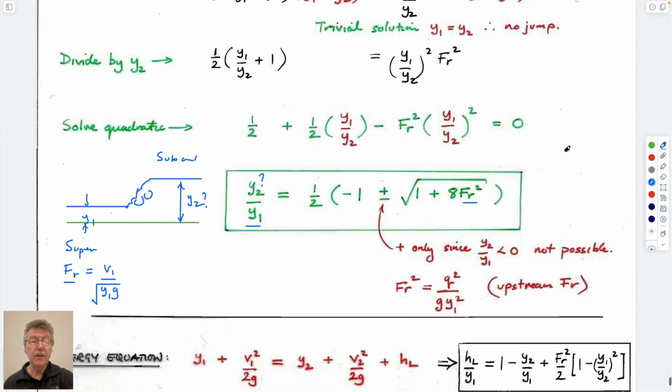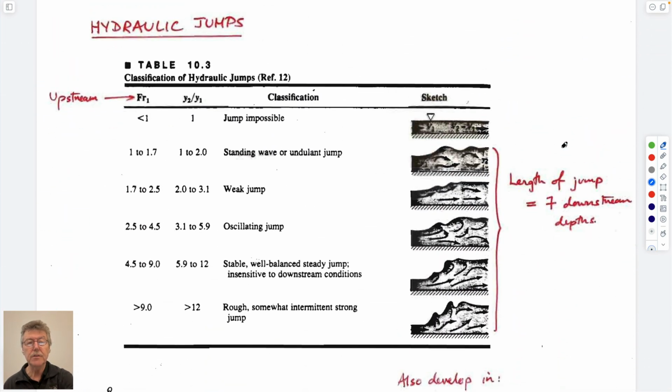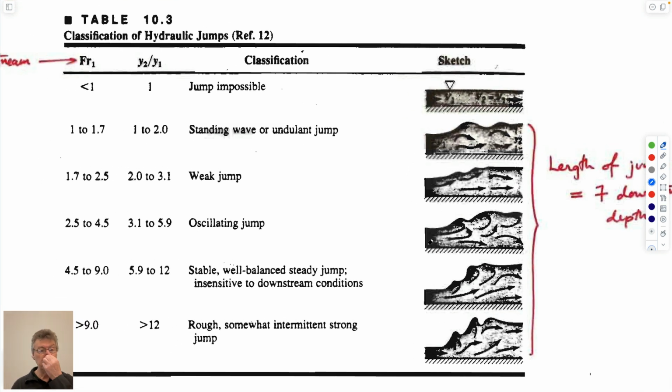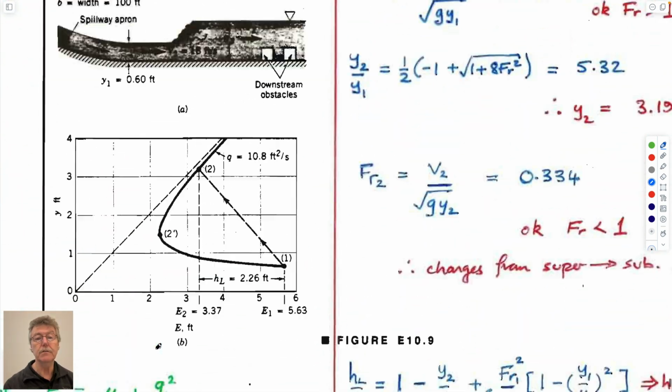And that might seem esoteric, except that if you figure out the parameterization of this, if you know the magnitude of the Froude number and you know the upstream depth, you can calculate what the downstream depth was. So there are cases where you don't have a jump, cases where the jump is large, larger, largest, defining the magnitude and exactly what it looks like. So that's it, and that is probably it for rapidly varying flows. We've covered all three.